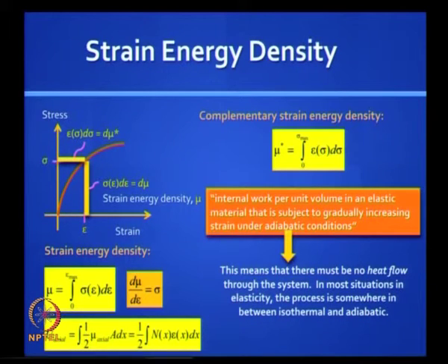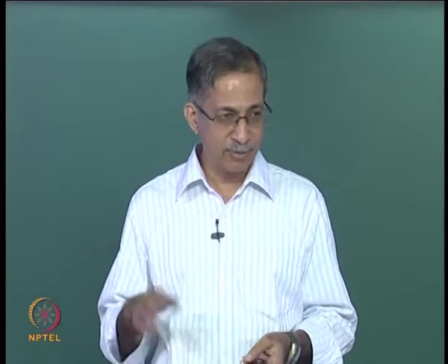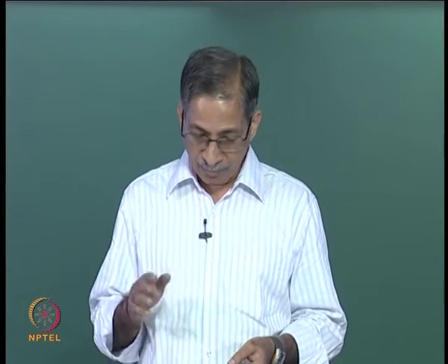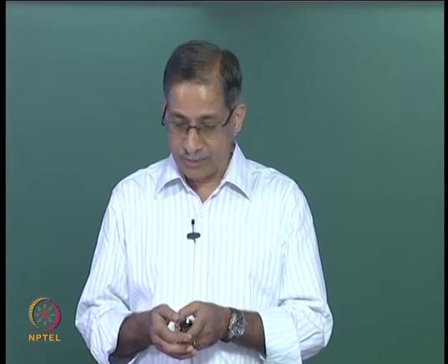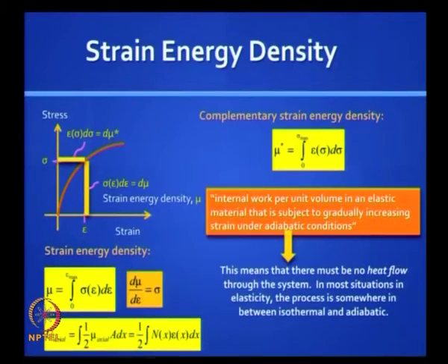Here you visualize the incrementing of energy coming from an increment in the force or the stress rather than in the displacement. You can do loading either displacement controlled or force controlled. So if you do it force controlled, then the product, which is also energy, would take this form, and we refer to it as mu star, and it is the other complement of the rectangle which contains the total energy. Sometimes it has a physical meaning, often it does not.